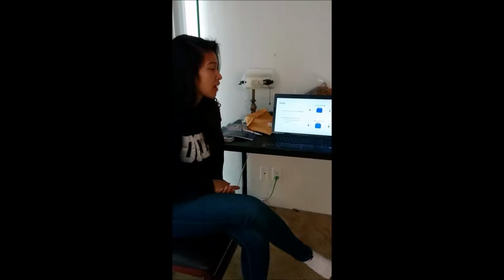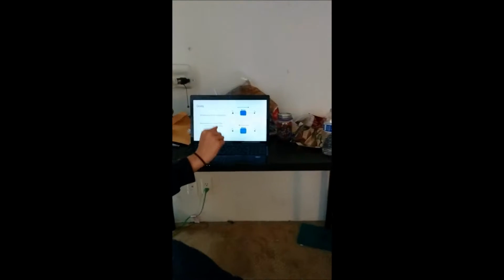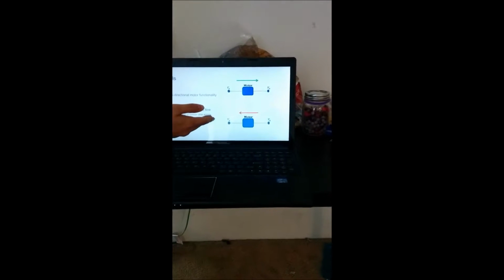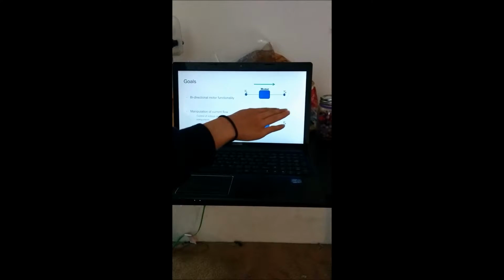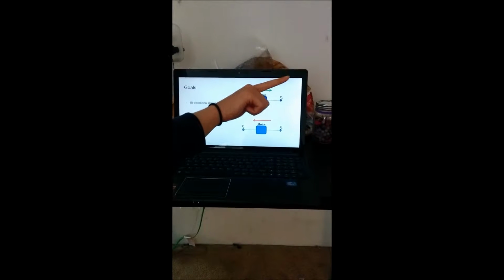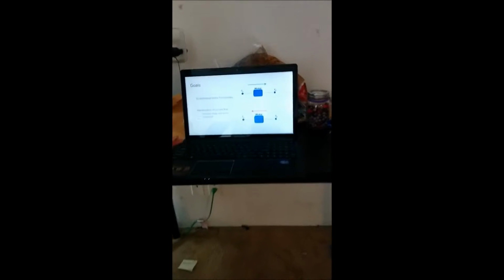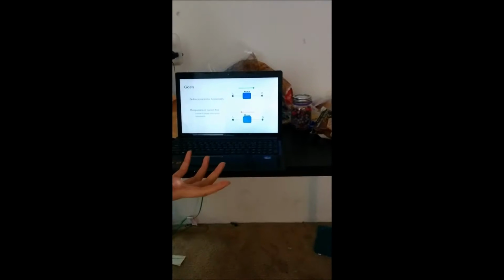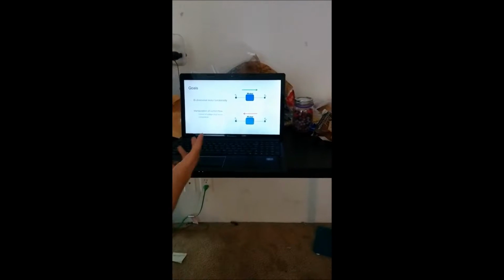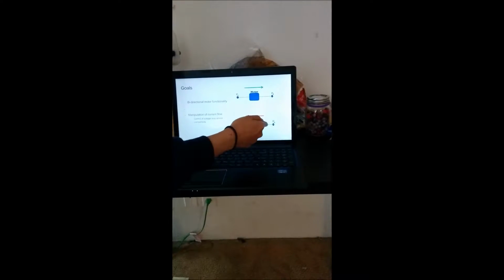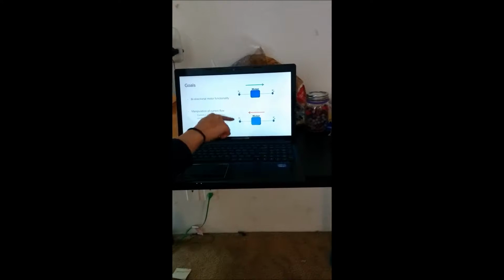So this implies that we have to manipulate voltages at either side of the motor on either node within the circuit. So for instance, in the first case, we would want the voltage at node V sub A to be greater than the voltage at node V sub B such that current would flow across the motor toward the right. And alternately, we would want to create a circuit such that we would be able to interact with it to induce voltage to be greater at V sub B than the voltage at V sub A. And our project was basically figuring out how we could find a way to do that.